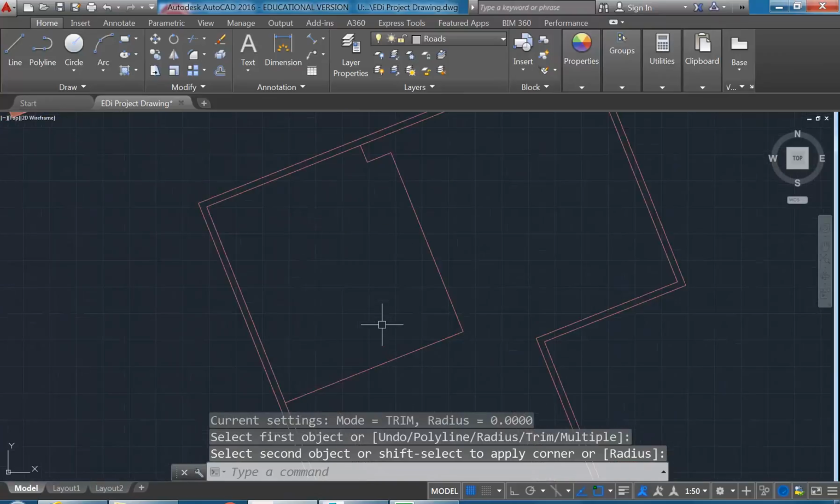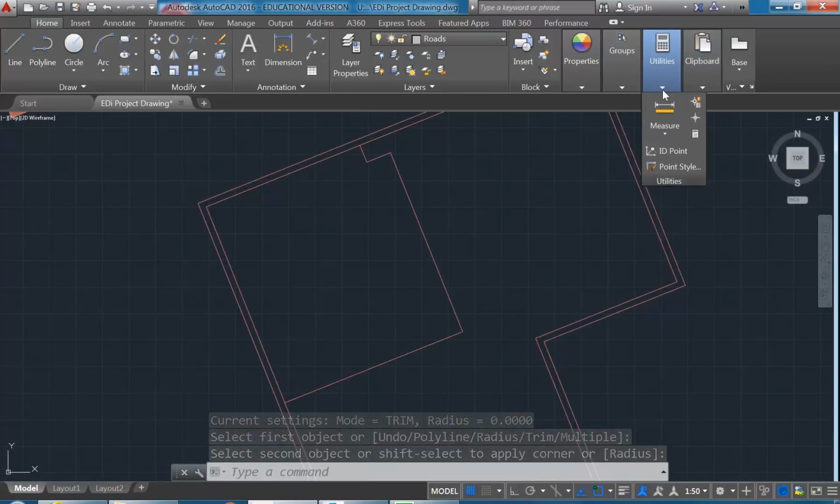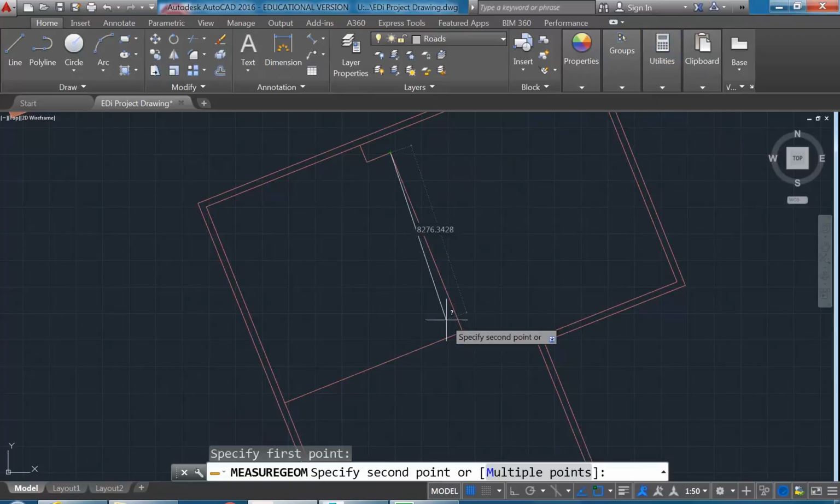We should then have an outline of the room, and I can at this point check the measurement for this wall, and you'll see that it may be different to what you've taken. And this can show you how things that seem perfectly square, this room probably seems like it is at an exact right angle, but we know now that it's not. So these walls are not perfectly square because that measurement there is 9091. But you've measured it with a laser measuring tool, and if you've got your drawings there, hopefully you can see the measurement, 9096. So it's only 5 mil, but that still means it's not perfectly square.